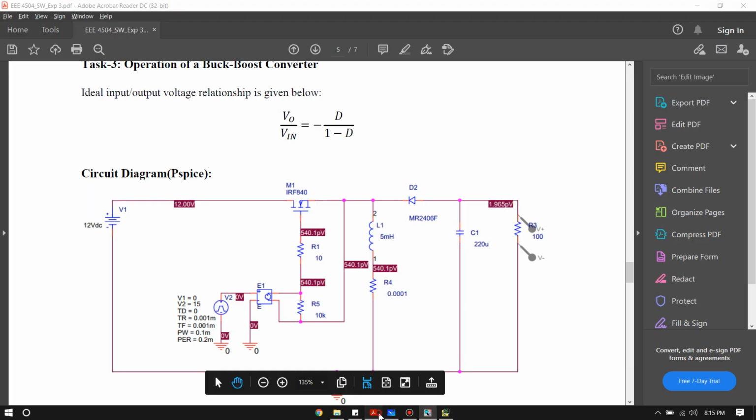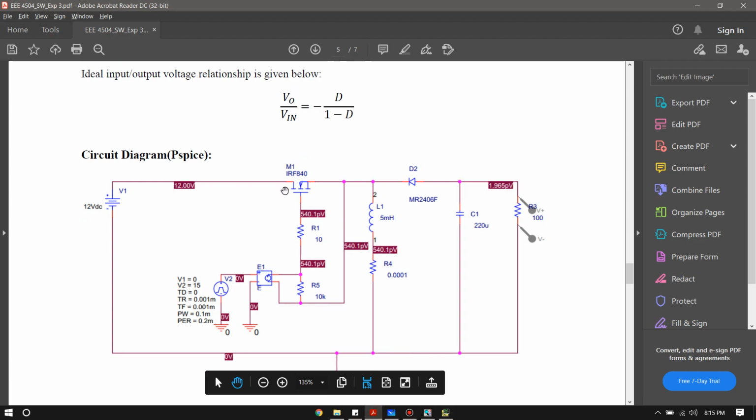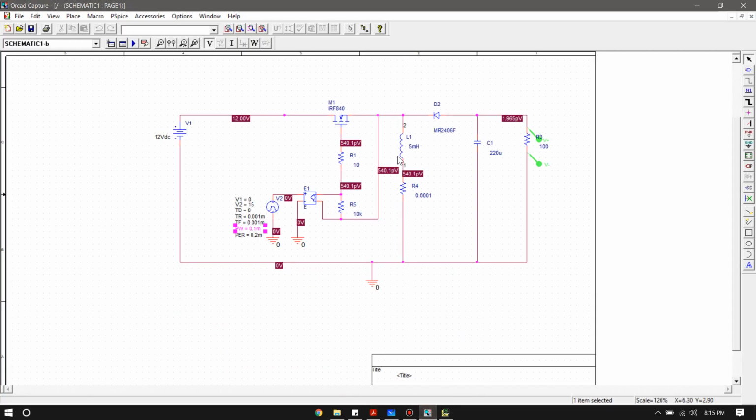And again, one thing you have to keep in mind is because of the MOSFET configuration, we need to use our voltage controlled voltage source to generate another ground, because we want the biasing of the MOSFET to be across the gate and source, right? As I explained before. So this is the circuit in PSpice, and I think all of the components have already been described.